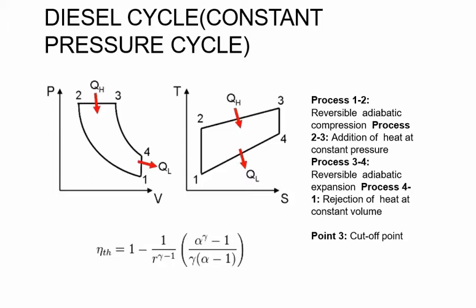The diesel engine is a heat engine. It converts heat into work. During the bottom isentropic process, energy is transferred into the system in the form of work, shown as W in. But by definition, no energy is transferred into or out of the system in the form of heat. During the constant pressure process, energy enters the system as Q in.